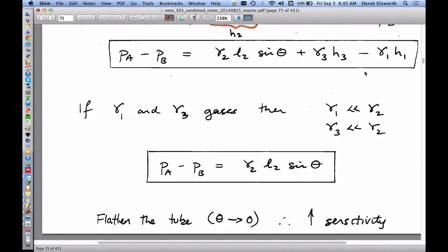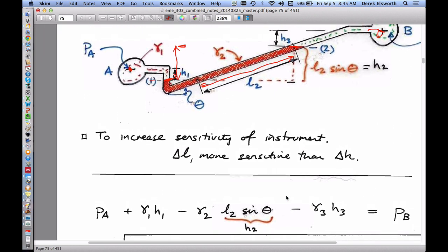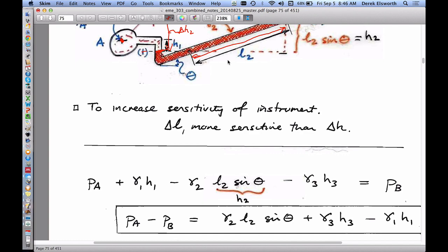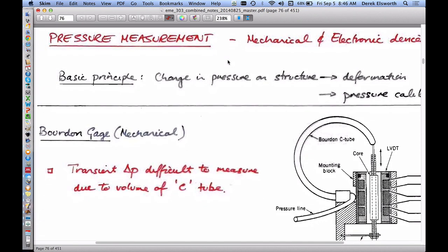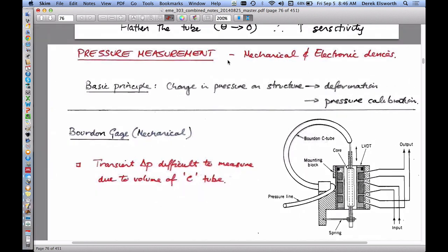And not surprisingly, the expression is that if you measure the length along the rise of that manometer and its inclination, that gives you a proxy. This is basically the change in height, delta H2, that exists between these two points. So the height between here, this would be, if you like, delta H2. Sorry, straightforward. So manometers are what have been used since the time of Isaac Newton. Still very robust. There are other ways of measuring pressures, of course.